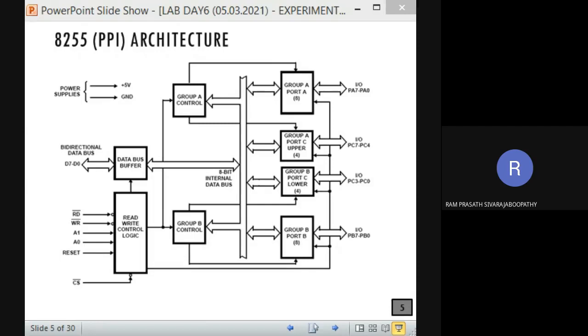So now you know an 8-bit address means you will have 8 bits. In that, the first 6 bits, that means 100000. This first 6 bits I am going to use as an input to a circuit. For the circuit with 6 bits input, it has to generate logic 0 only for this combination of input.